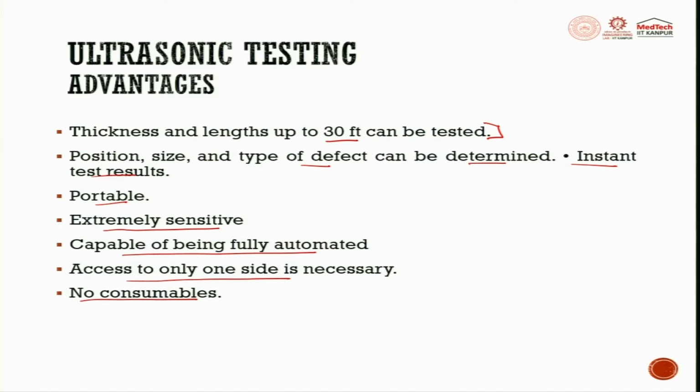There are certain other advanced tests in the ultrasonic systems itself, like immersion testing. In the immersion test, there is a tank of water, and the water acts as a coupling medium that allows the sound beam to travel through. The ultrasonic machine is mounted on a movable platform on a bridge side of the tank, and it can travel down the length of the tank. Through transmission also happens, where the transmitter and the receiver work with the test beam or sound beam. So we are talking about ultrasonic testing from the viewpoint of vibration and the sound beam as well.